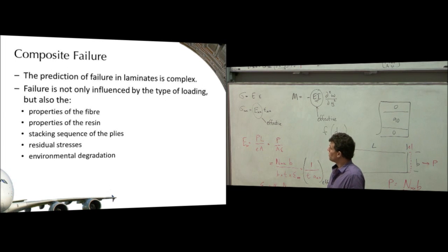So there's a cross-sectional area, but the property that defines the underlying strength of the material is a critical stress. With composites, it's a little bit trickier to do that because they're made from stacks of different orientations. There's all sorts of complexities to them, so it's very hard to define what the critical stress for a composite is. In fact, in most cases, there's probably multiple critical stresses depending on whether we're loading the matrix, whether we're loading the fibres, tension, compression. So there's lots of complications. When someone says how strong is a composite, it's actually a kind of silly question. You can't answer that very easily.